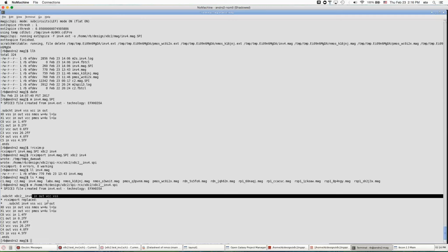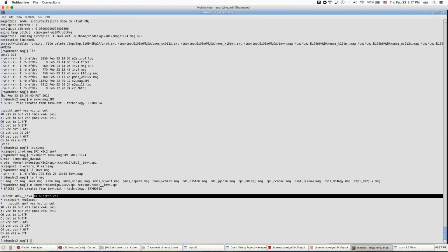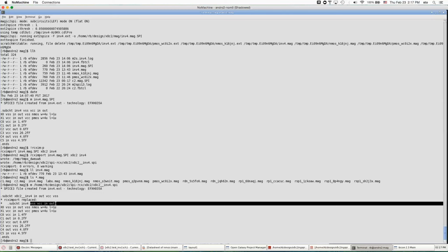In this particular challenge case, there are trim bits with brackets in them, which is irrelevant for the purpose of this Zoom session, but you'll notice that they're different. The ports in Magic have an index, so you can control the ordering in Magic, and you could force Magic to natively give you the correct port order.